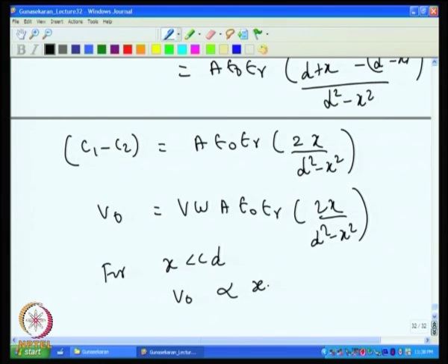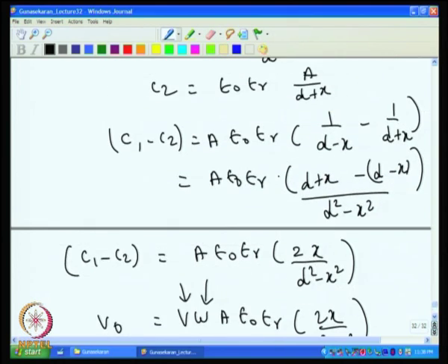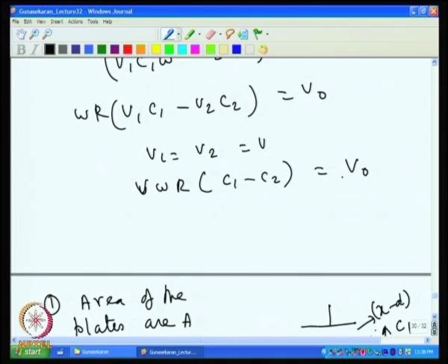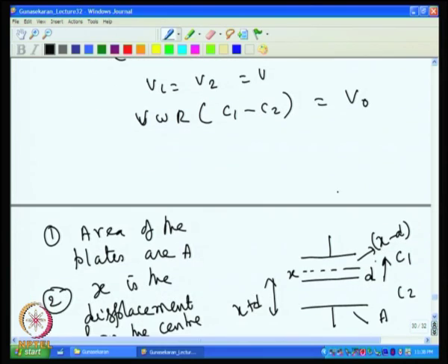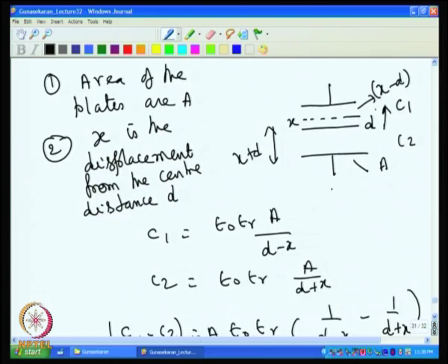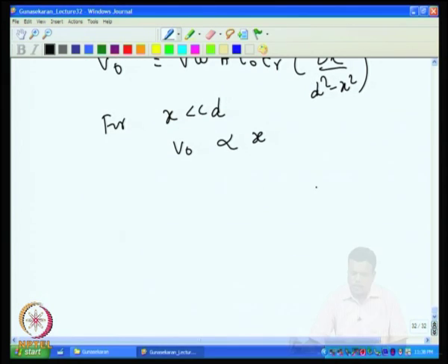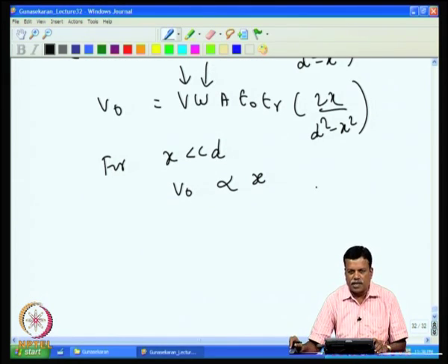But here again you will find that it is sensitive to omega, it is sensitive to variation in V, and it is sensitive to that epsilon r variation. What we had planned is that when the moisture varies, it is supposed to cancel off both. That is not really happening, because our capacitor currents are still there. Only if it is a null method can it be cancelled. But here all these things still have effect. So, even this is not very accurate, and it is not very linear.